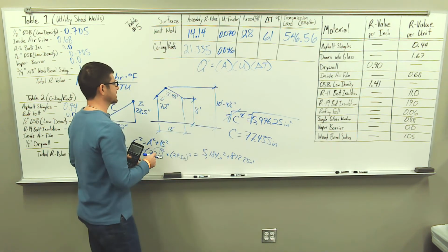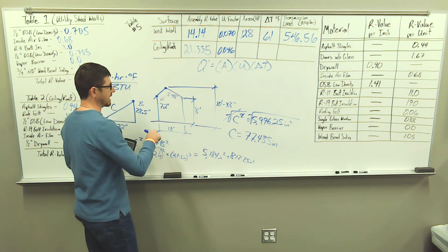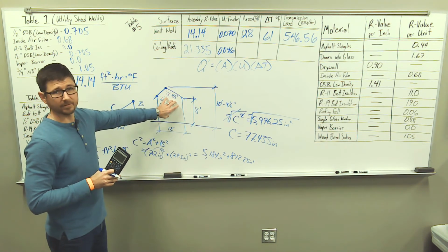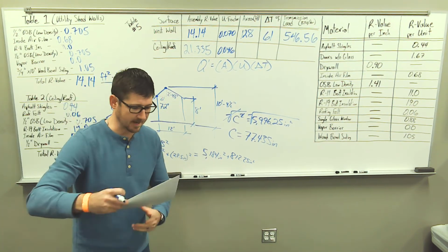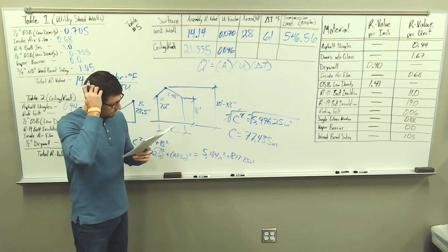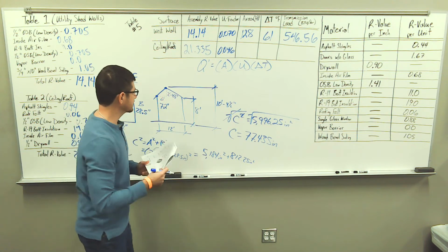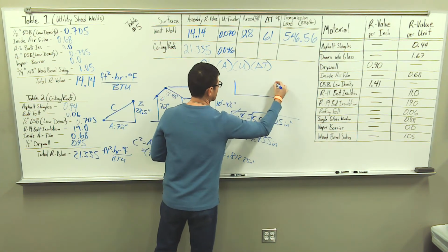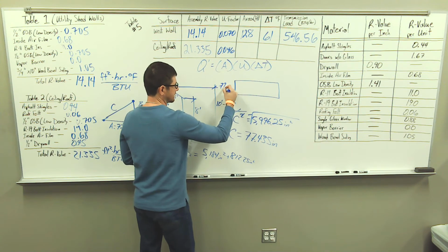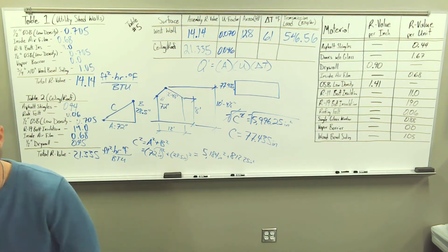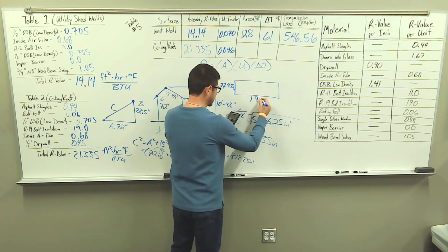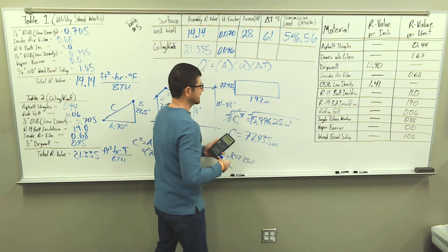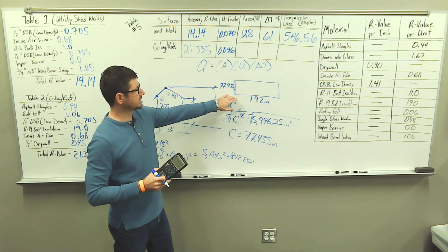Okay? And so now we need to multiply this, from this elevation view, by the depth of our roof. And looking on page 5, our roof depth is going to be 16 feet. So I'm just going to label this 77.435 inches and 16 feet. We need to convert that into inches, so 16 times 12. That's 192 inches.